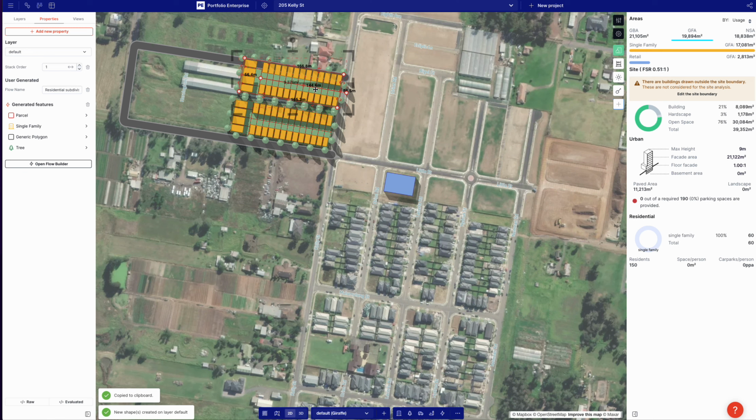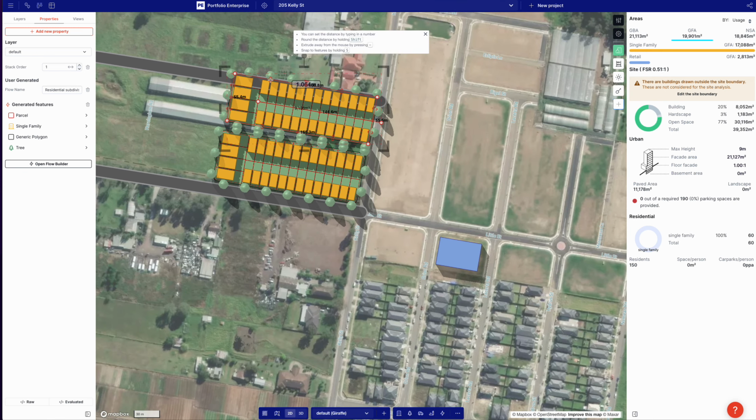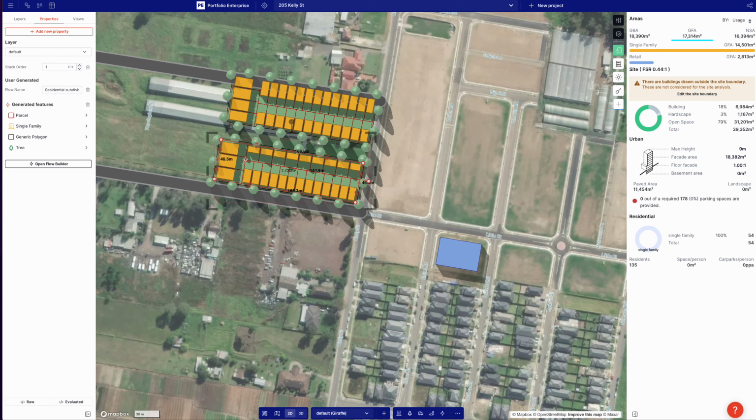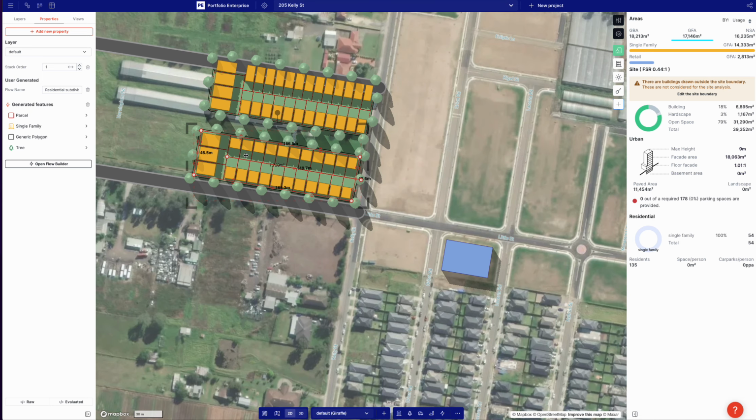All right, especially if we shrink them in slightly and shrink this guy in slightly. Now you can see the frontages are growing there because the minimum size is 270 square meters, and so that's why those frontages are growing.